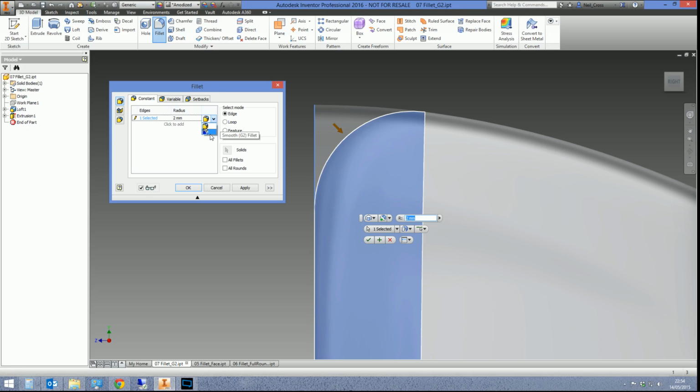The G2 fillet applies a very, very minor aesthetic change to the contour of the fillet. The tangent fillet, if you think of the blend of the fillet here as it comes away from the final edge here on the solid model, it's coming out at a perfect tangent. Right? If you think about a tangent is a circle. Yeah, it's a perfect circle. So you could stencil a circle onto this model, and that arc would follow the exact shape of a circle.